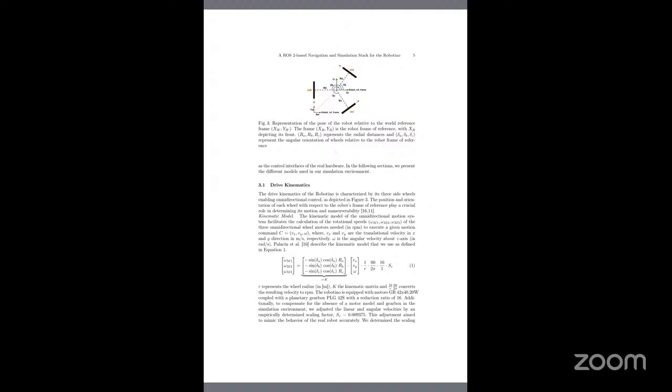Why is this scaling factor required? In simulation, 1 meter per second. Okay, but in real robot, it is 0.7 meter per second. So in that case, using the scaling factor, we can change the speed. Why have they used the scaling factor? Because the robot in simulation as well as the real robot should behave in a similar manner. That's why they have identified an empirical scaling factor.